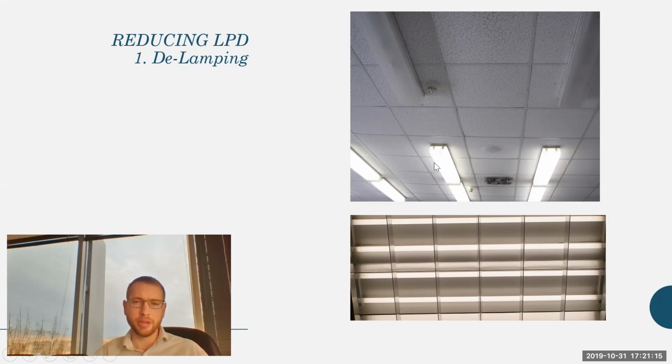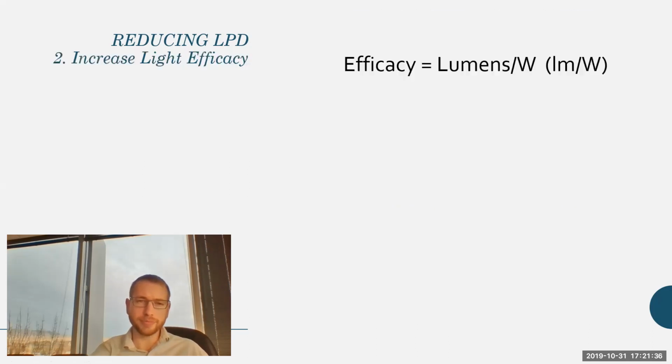We'll talk about measuring illuminance in the next section. If you're getting adequate illumination on the surfaces in the space, you might be able to just turn off a couple of lights and take bulbs out of the fixtures. Some of these fixtures contain 4 different bulbs, and they might just need 2 of them. So that's one cheap, very easy way of going about it.